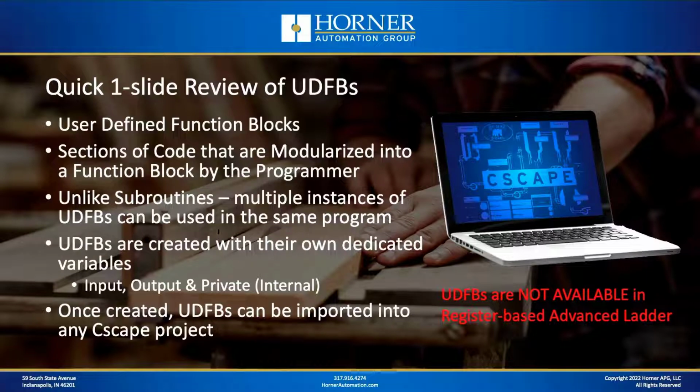When you create a UDFB, you create it with its own set of dedicated variables. Then when you add an instance of a UDFB in a future project, for every instance you add, there's a unique set of variables for that instance. So that means, of course, you can have multiple instances. Again, a big difference from subroutines, for instance. And once UDFBs are created, they can be imported and used in any future Cscape project.